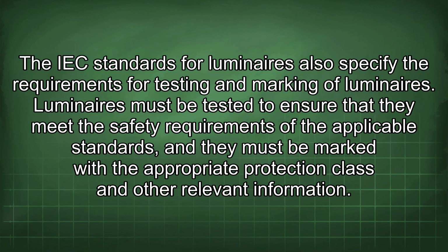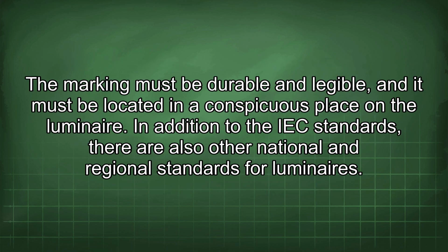The IEC standards for luminaires also specify the requirements for testing and marking of luminaires. Luminaires must be tested to ensure that they meet the safety requirements of the applicable standards, and they must be marked with the appropriate protection class and other relevant information. The marking must be durable and legible, and it must be located in a conspicuous place in the luminaire.